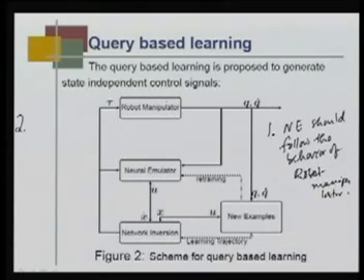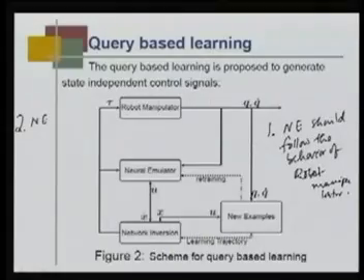What is this second point? The second point is that now we ask this question to the neural emulator: given a target point, what should be the control input? We give that control input to the actual robot manipulator, and we see if the manipulator goes to the target point. If that is the case, then we would say that the neural emulator is properly mimicking the robot manipulator.